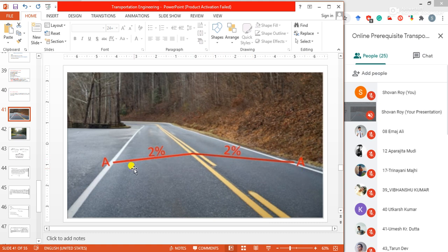During construction, normally we can make the top surface of our road like that. So easily water can drain off from the road surface, and sometimes I already said that the drain is also important with road. Along the road we should provide a drain or drainage system so that the water can easily drain from our road. So as soon as possible we should drain off the water from the road surface,